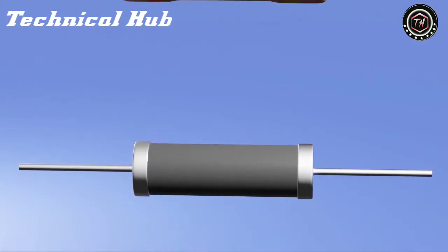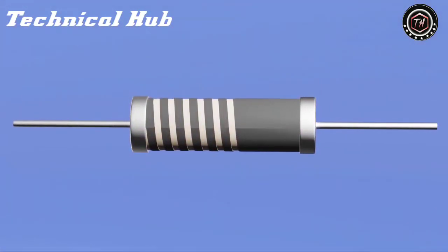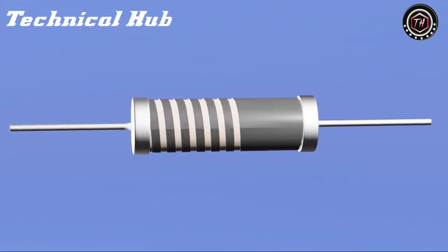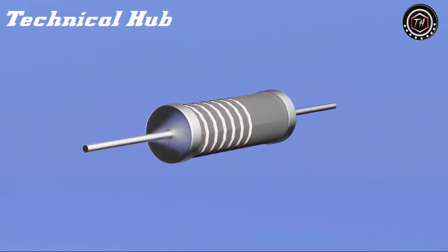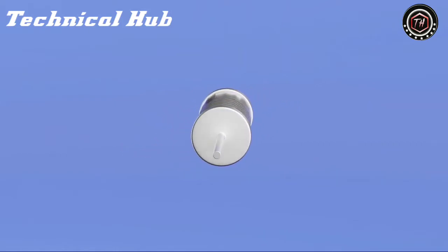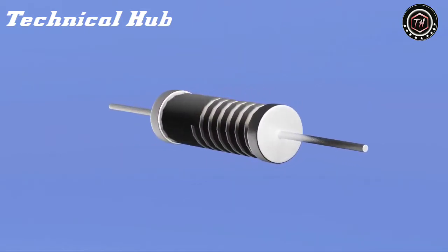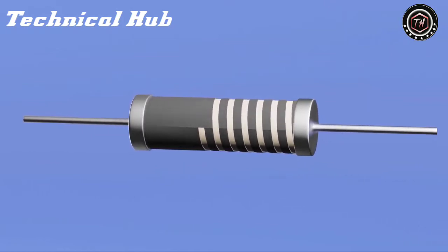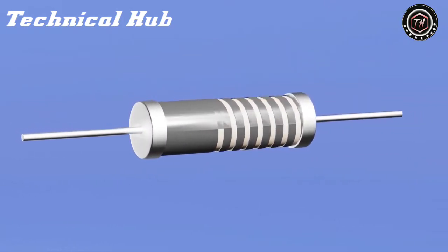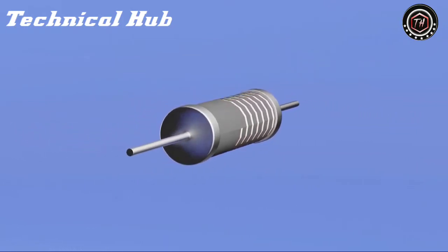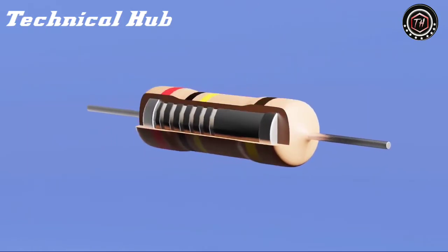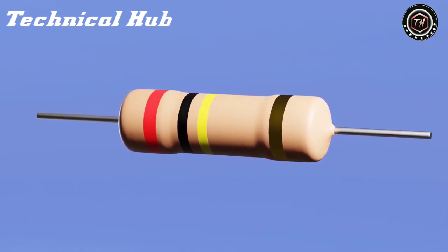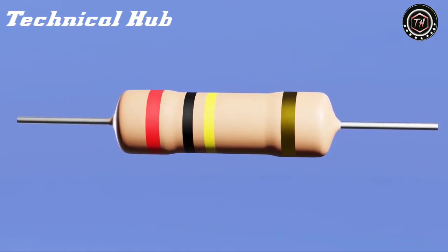And the third option, is by means of a ceramic cylinder covered by a carbon film, which is cut in a spiral until obtaining the desired resistance. In other words, a carbon wire is gradually created to increase the resistance to the desired value. As generally these resistances are so small, it would be quite difficult to print what their value is. That's why was invented a code of colors, by which we can know its value in ohms, even without numbers.